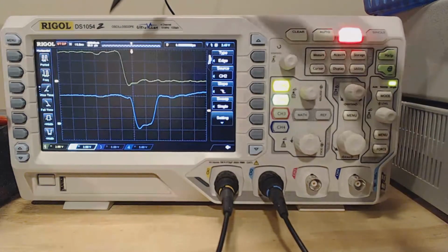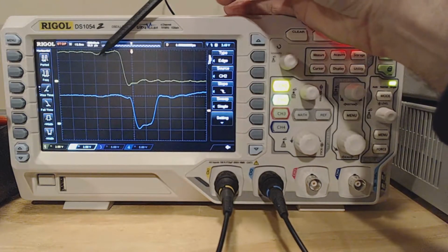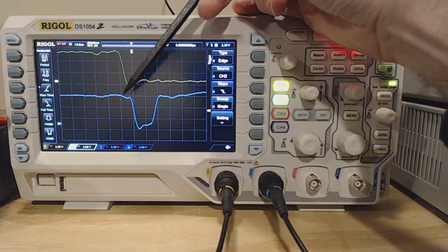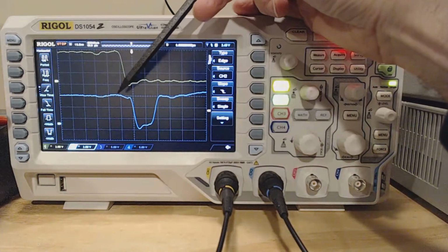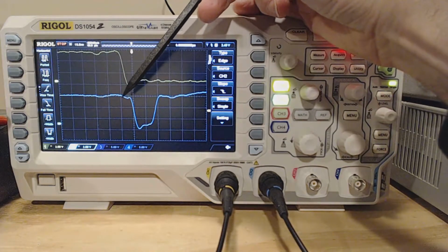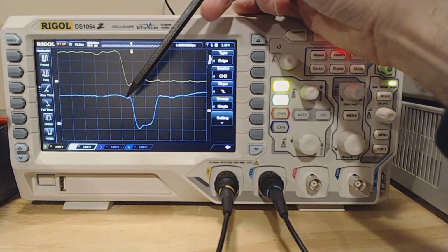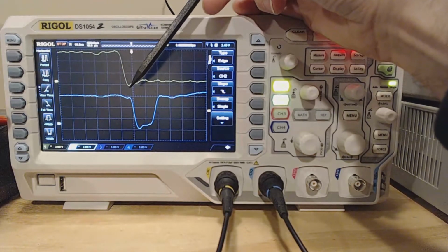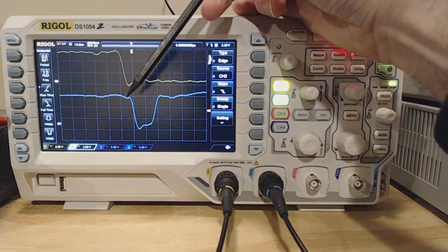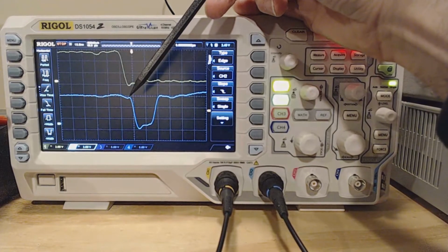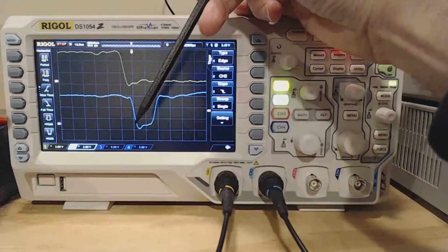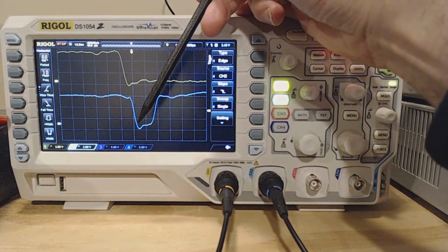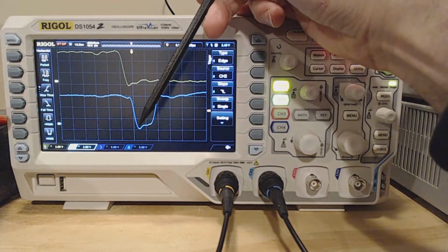Now we have triggered, and essentially what happened is that here, when our input went from high to low, in a relatively short amount of time, maybe 5 nanoseconds or 7 nanoseconds, the effect of that A input going low propagates to the output of the OR gate, sending the output of the OR gate low.